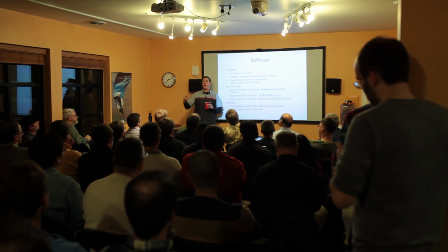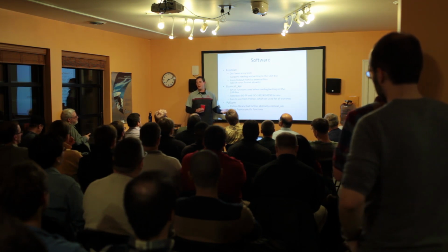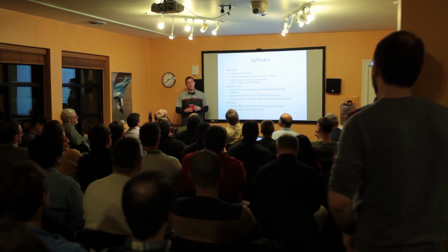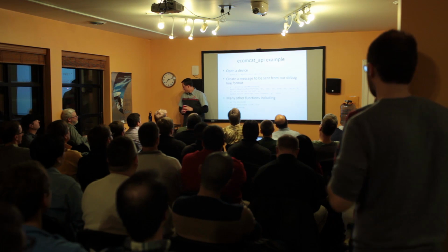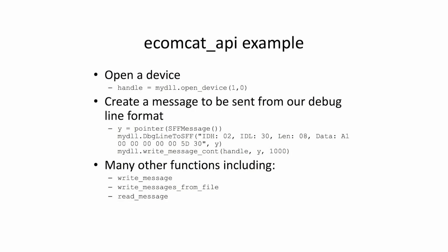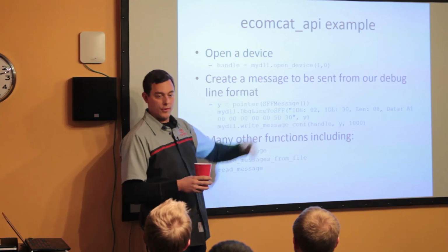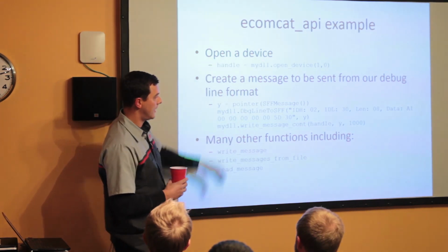They did a lot more proprietary-based stuff that I reversed out. So I figured if I'm going to reverse it out, I don't want someone to have to do that again. So I'll write this library, and you can just use it and not worry. So how does all this work? You want to write to the CAN bus. Before it was like, buy this thing, do all this work, maybe get Vector or whatever, but we wrote this Python library. You stick that thing in USB, connect it to OBD2, open the device.